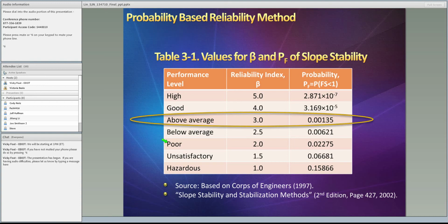So how do we consider the bias? The arching bias uses the ratio between the finite element eta over the computed eta, which is a semi-empirical eta. We summarize the 41 ratios and divide by m, which is the mean of the eta bias. And we can also use this equation to calculate the variance of the load transfer factor bias based on the 41 finite element results.